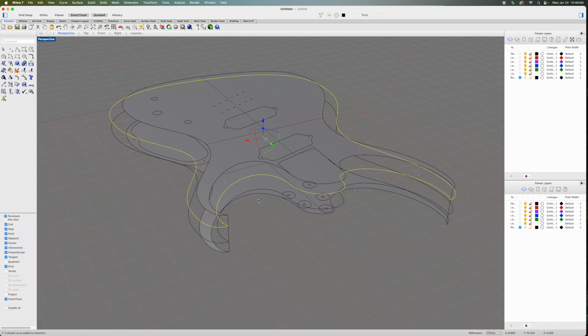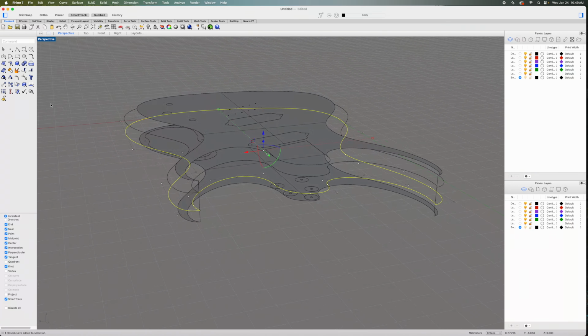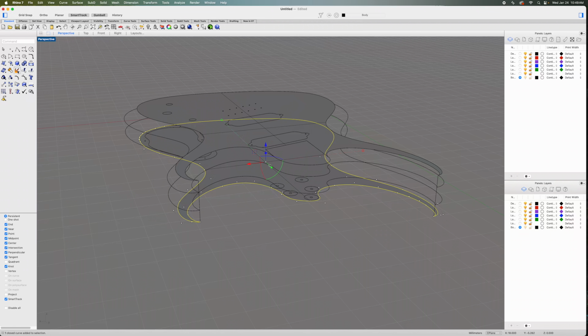Then I will do the same thing on the next line down below. I will explode it, deselect these elements, then press J and rejoin the rest of these lines. Do the next line down below that, explode it, deselect the elements, then click J and then return. And then I will come down to the very bottom one and do the same there. Explode it, deselect the curves at the front, and then join the rest back together again.